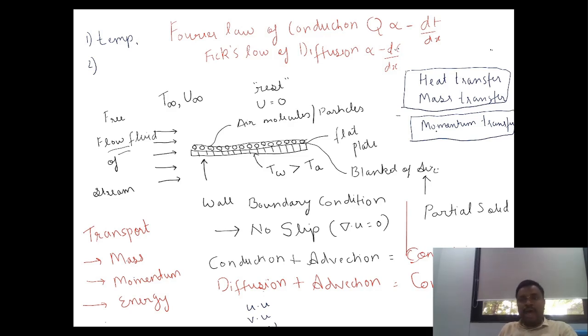So you need special iterative techniques in CFD to solve momentum transfer so as to absorb its non-linearity. Linear equations can be easily solved, and we have certain equations derived from these convection diffusion equations, but the same cannot be used for momentum transfer. We need separate, advanced iterative techniques so that we can absorb the non-linearity present because of these terms. So this is the first reason.